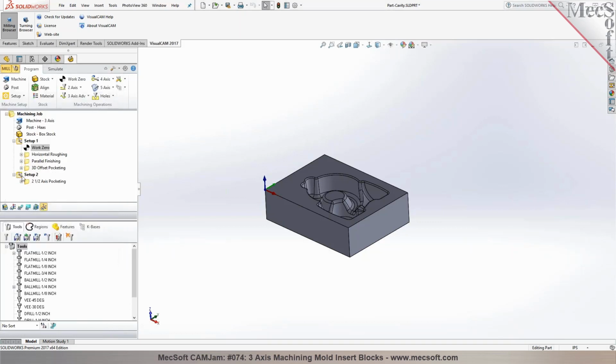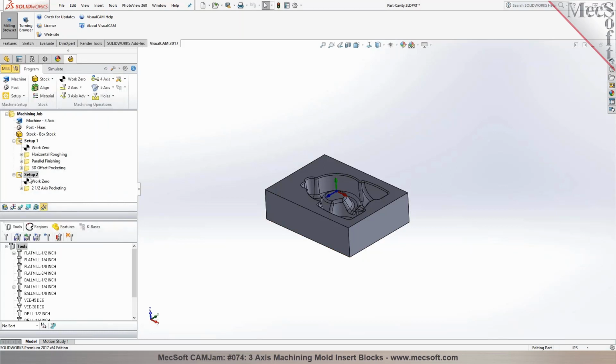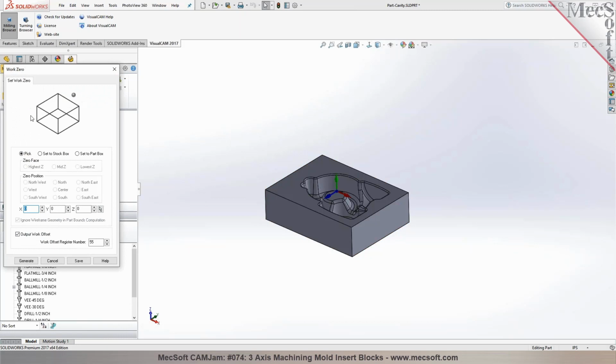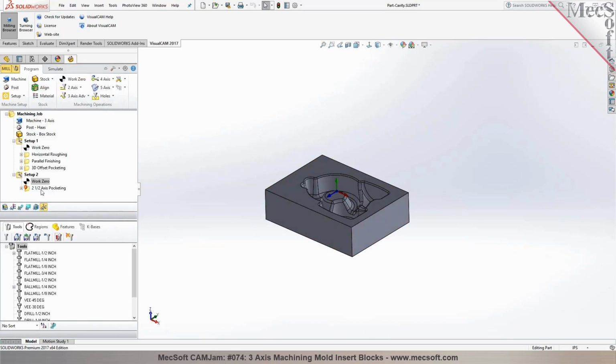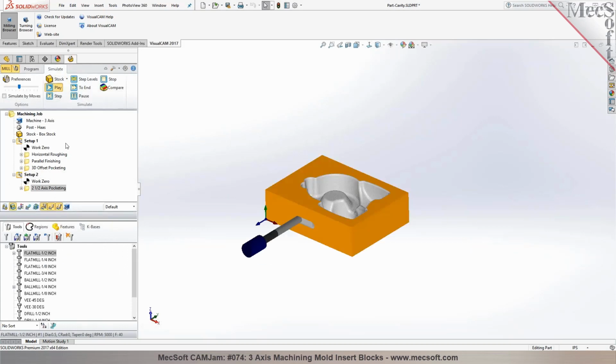For machining of the side face, you could be using a fixture offset number G55. So you can basically output them. We're not going to visualize them side by side. We're just going to show how you have it programmed in here. This would be a G55 coordinate position, where you can specify where it needs to be. I can specify to maybe put it to the right, over to this corner, and that would represent where your origin is.